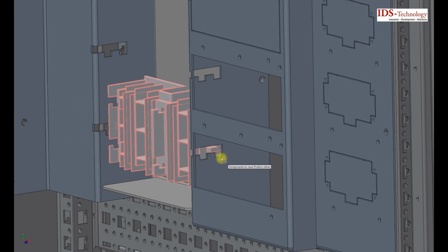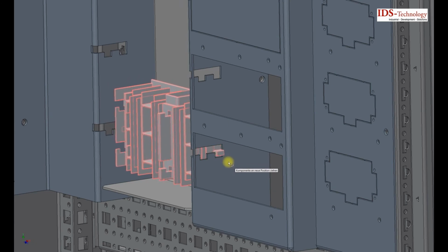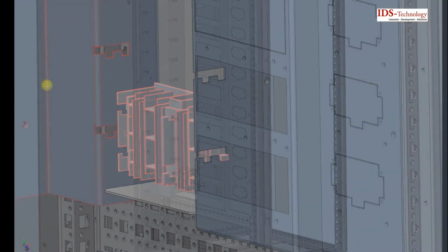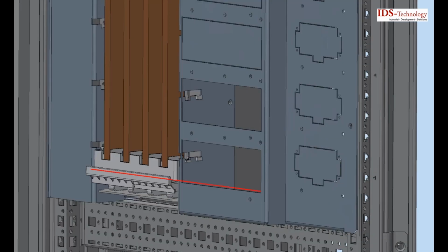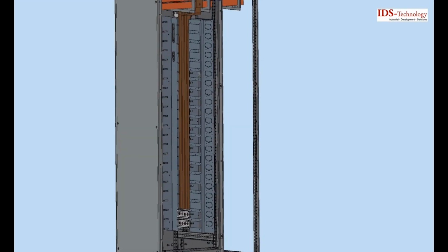The push-in and drop technology gives a strong short circuit withstand up to 80 kA per segment, optional 100 kA for the VBBs. Necessary blind shutter and operating shutter make the whole a fully insulated, non-touchable vertical bus section. The production of the EST wall will be in your hands. The EST wall can be manufactured by 1, 2 or 3 pieces, depending on bending machines.